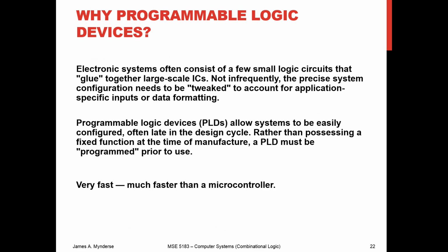So your PLDs, your programmable logic devices, are something that are going to take some logic circuits and jam them together, and they're going to be easy to program. They're fast because they're not running like a microcontroller. A microcontroller is running a set of instructions, running in series. PLDs are actually like logic circuits, where they're running in parallel and they're bounded by propagation delay, not based on the cycle times. So they can be very fast and they can be very configurable, as long as you understand that you have to fit everything within the available amount of logic that's on it.